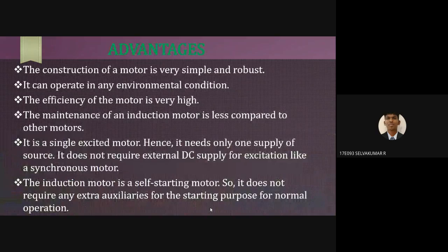The major advantages of three-phase induction motor are that the construction of the motor is very simple and robust. It can operate in any environmental condition. The maintenance of an induction motor is less compared to other motors. It is a single excited motor, hence it needs only one source of supply. It does not require external DC supply for excitation like a synchronous motor. This is one of the notable advantages of using three-phase induction motor.